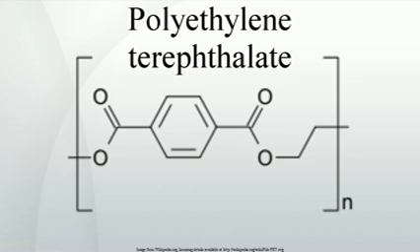If only small amounts of comonomers are used, crystallization is slowed but not prevented entirely. As a result, bottles are obtainable via stretch blow molding, SBM, which are both clear and crystalline enough to be an adequate barrier to aromas and even gases, such as carbon dioxide in carbonated beverages.